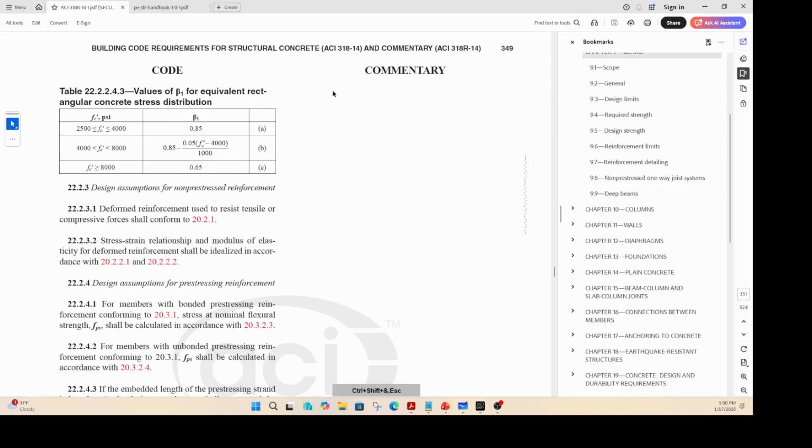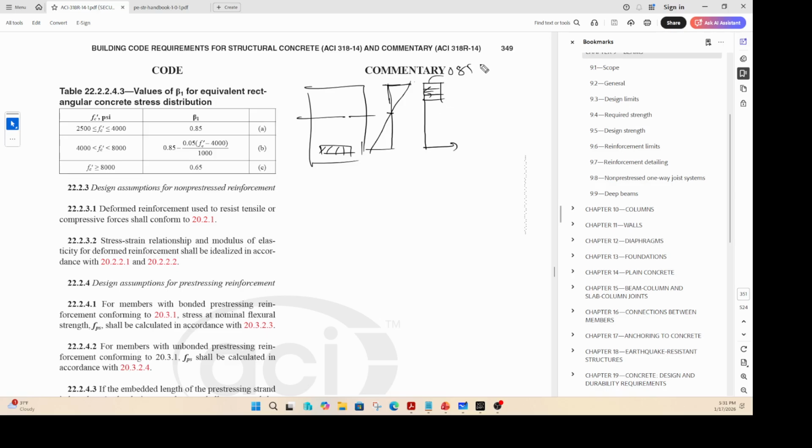Now, how do you calculate the depth of the neutral axis? That is something we missed last time. So here is our beam, right? So that is your tensile reinforcement, and let's say that is the neutral axis, and here is the strain diagram. It cuts there, right? And you have your Whitney stress block, 0.85. This width is 0.85 fc prime.